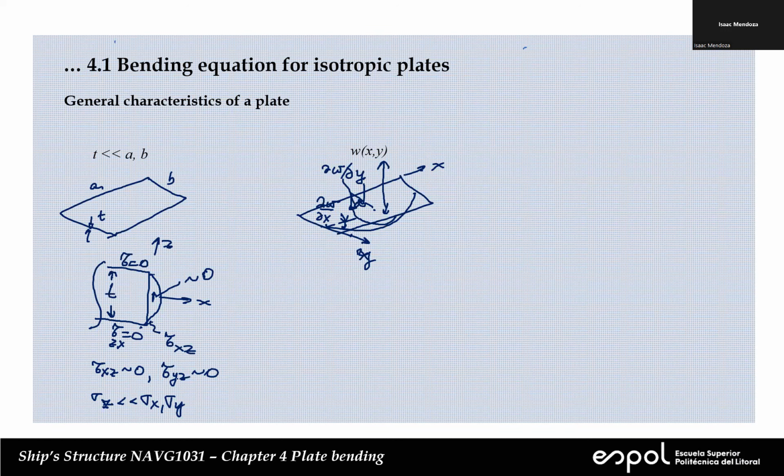So from now on, in this chapter, remember that derivatives are not something like this. They're going to transform into something like this, partial derivatives. So, for example, when you say shear force, that's incorrect. Why? Because we have two shear forces. When you say bending moment, now you have to tell me it's either bending moment in X or in Y. So we need to be more specific because the two directions are very important.